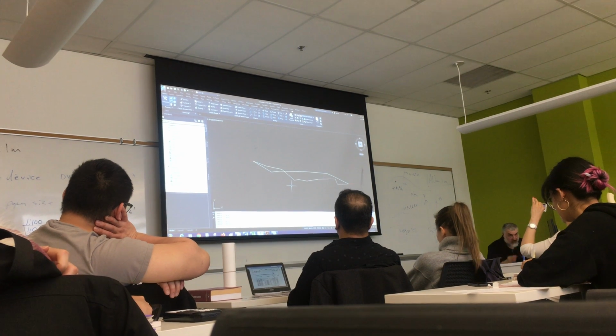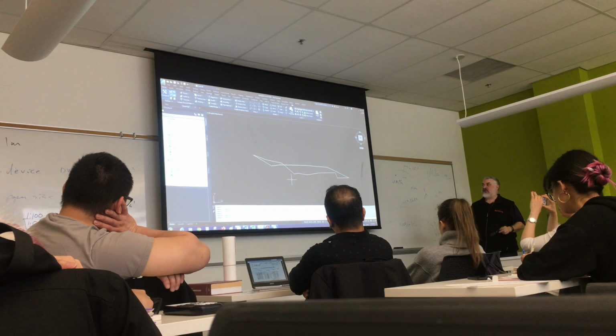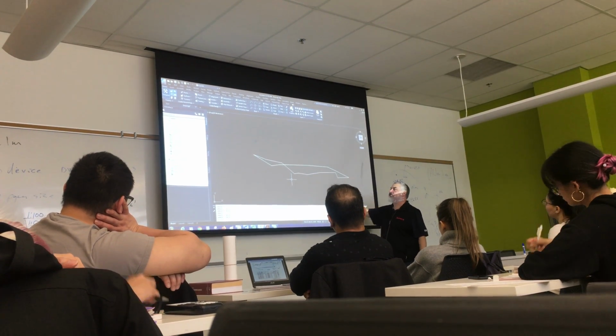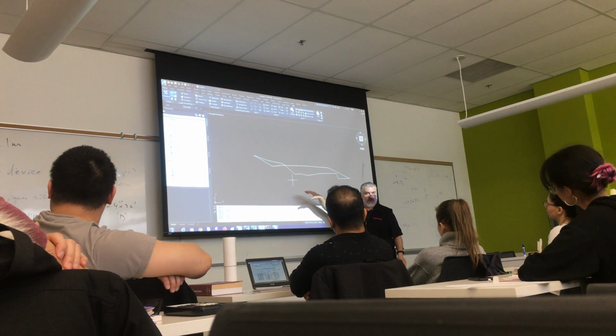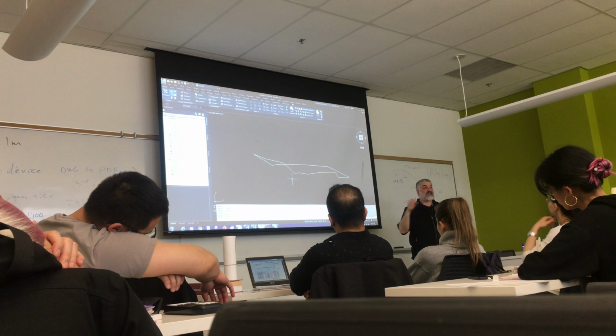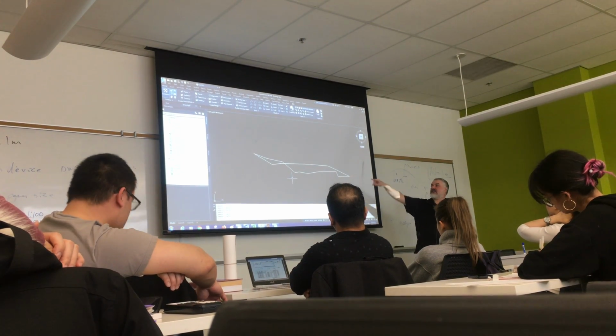So those areas, total end area of cut, total end area of fill, must also be annotated on the drawing. Cut equals so many square meters, fill equals so many square meters. Put those two numbers on your drawing as well. Okay? That's an analysis thing. You can't do that until the design's done. So draw everything and then get these two end areas.